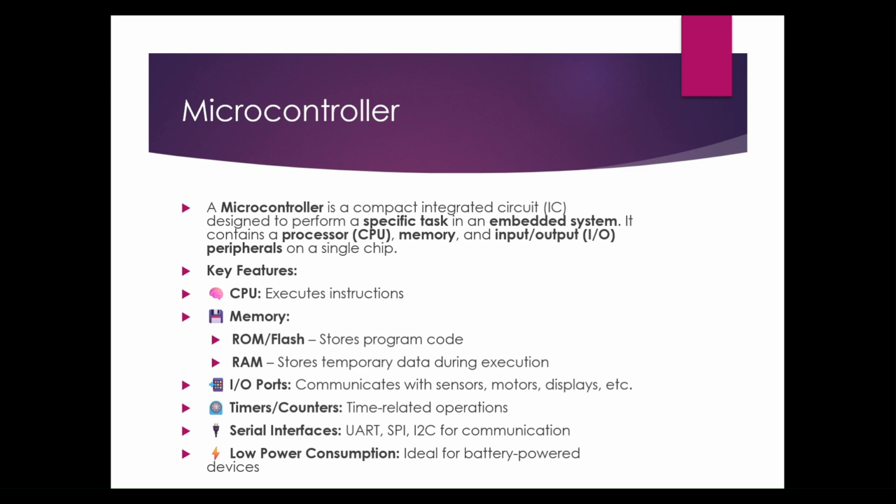Serial interfaces: UART, SPI, I2C for communication. UART is Universal Asynchronous Receiver and Transmitter, SPI is Serial Peripheral Interface, and I2C is Inter-Integrated Circuit for internal communication. It has low power consumption, ideal for battery-powered devices.